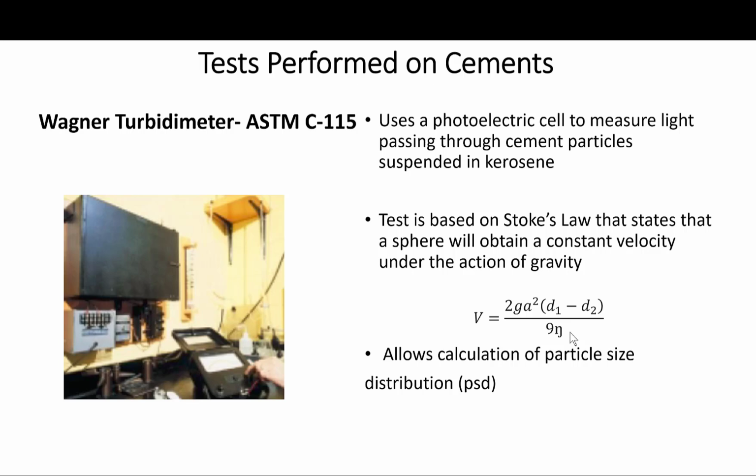In these calculations, the assumptions are made that, first, the particles are spherical. Second, the flow is truly viscous. Third, particles are in the range of 0 to 7.5 micrometers. They all have a uniform size of 3.75 micrometers. So these are assumptions, and they're not all true. You have to keep that in mind.